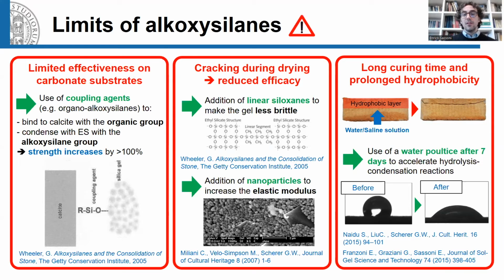Other known limitations of alkoxysilanes are their tendency to crack during drying, which again reduces their efficacy. To overcome this limitation, different strategies have been proposed, such as the addition of siloxanes to make the silica gel less brittle, or on the other hand, the addition of nanoparticles to increase the elastic modulus of the gel.